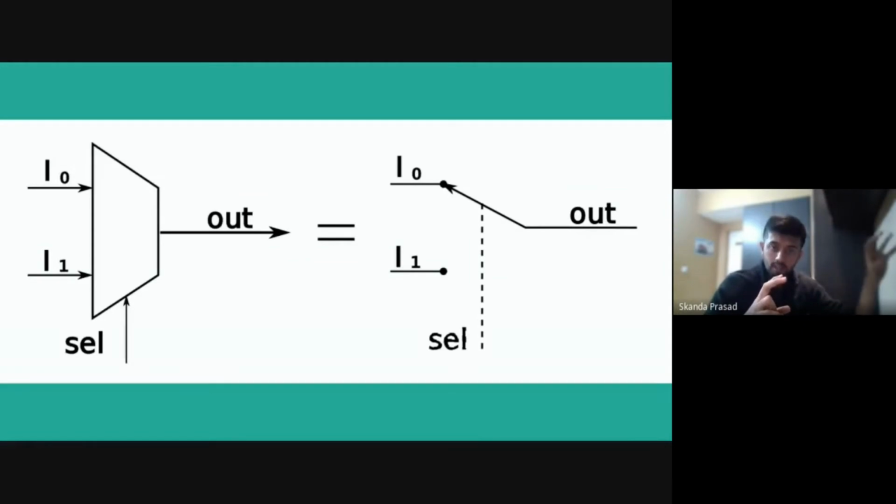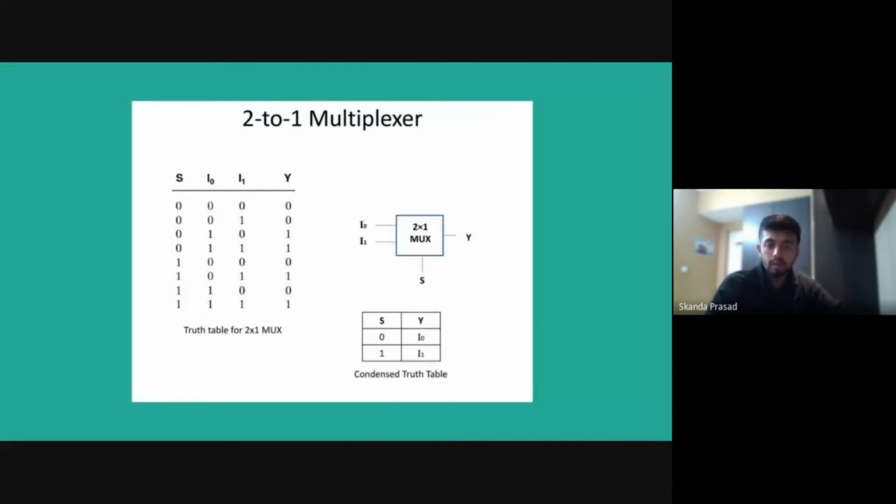One has the addition logic and another has the subtraction logic, which we will build later on. Whenever I select 0, it will perform addition and give the final result. Whenever I select 1, I'll know that there is a negative number. I need to use the same circuit, but with the negative number, so that it subtracts for me and gives the final addition. So that will be the application of multiplexers, which we will use. And yeah, the truth table, etc.